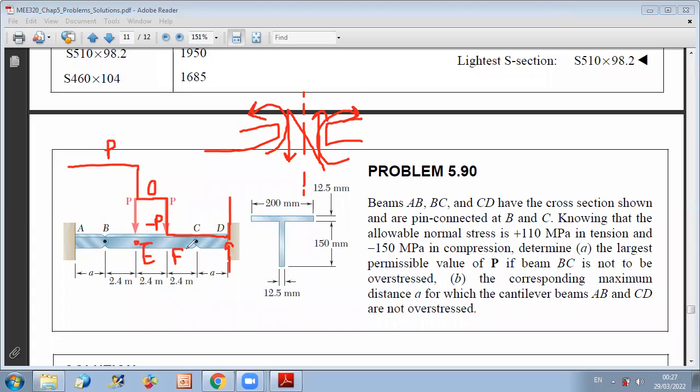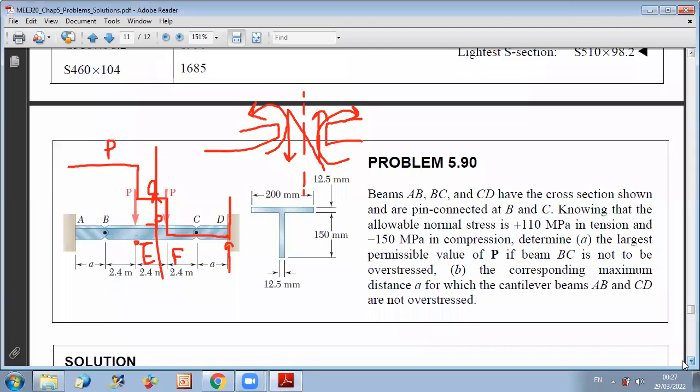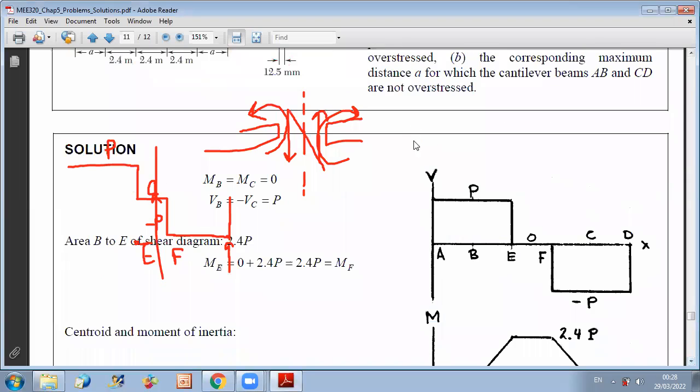So you can just plot the bending moment until the middle and deduce the other part by symmetry. While for the shear, you will have, if you want, symmetry with respect to a point, not with respect to an axis. It's anti-symmetry with respect to the axis, and you have symmetry with respect to the point. So if you draw the shear and bending moment diagrams, you can verify this. So for V, you have symmetry about point O.